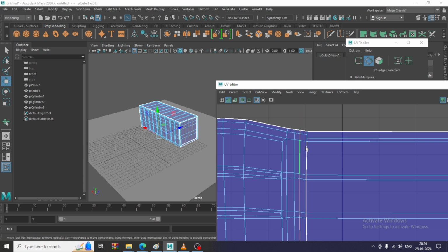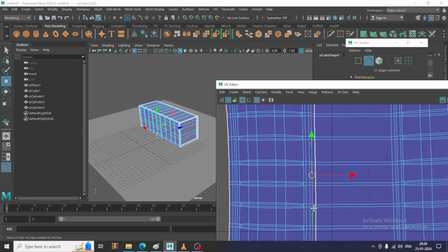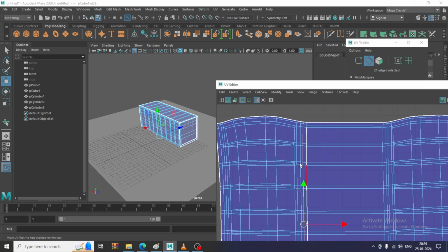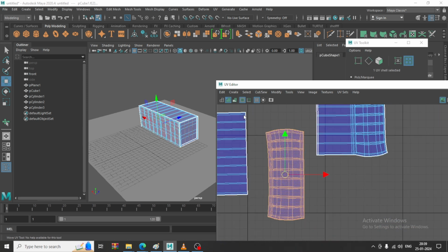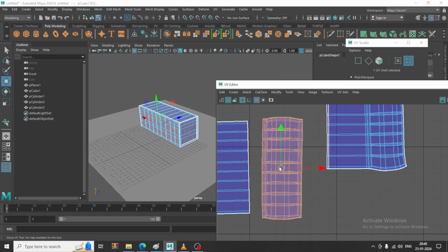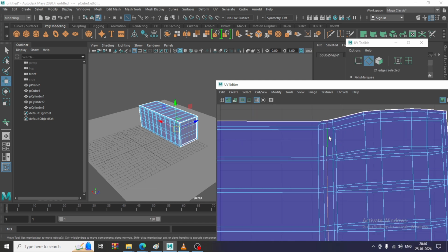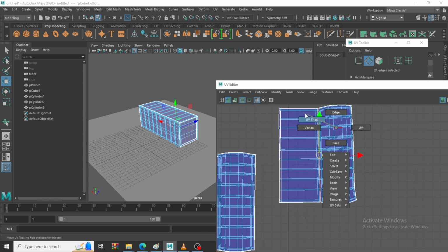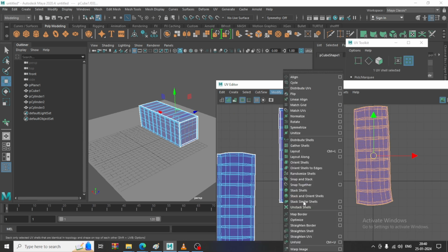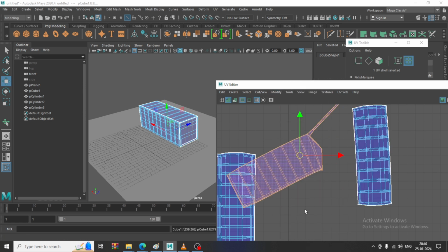So just select this, so just cut it, select this, push this out, modify and unfold it. You can try to make it straight, not a problem. So again go over here, select this, let's say cut again, push this out, modify, unfold it. Modify, unfold it. Oops.